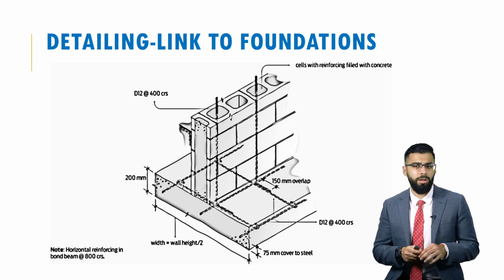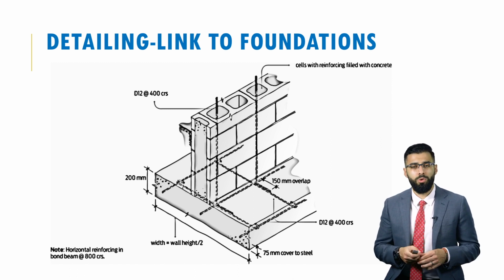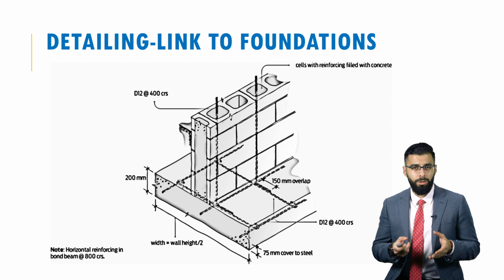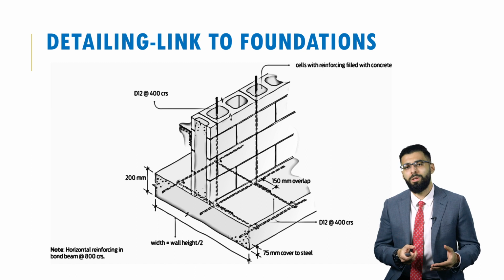Now, when it comes to design, another important aspect is the detailing that's involved. When I say detailing, I mean how the reinforcement, if you have reinforcement embedded in your masonry structure, links to other members. So in the example that I have on the slides, you've got a foundation system with embedded reinforcement. At the same time, you're constructing a wall, say, for instance, a retaining wall above the foundations. You have to link the reinforcement that's inside the masonry structure to the reinforcement that's embedded in the foundation system. If the connection is done in the right way between the reinforcement, then you ensure that your structure is durable, and that's why it's important.